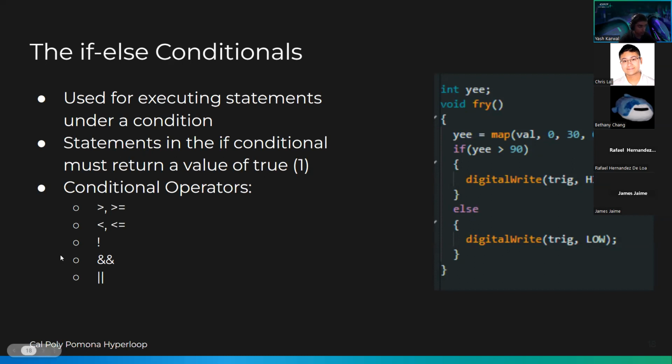So if those 2, let's say you have 2 inputs for now, are both high or both true, then it'll output a high or a true. If those 2 are not, so if this and this, but the other one is not a true statement, then it will output a false or a 0. The OR here does, if something happened, or if something else happened. So if either of those 2 are true, then it'll output a true.